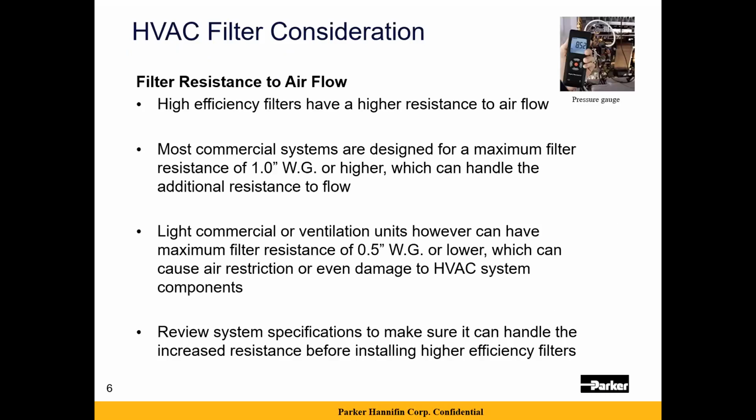So the first consideration is filter resistance to airflow. Generally speaking, as you increase filter efficiency, you will also increase that filter's resistance to airflow. Most commercial systems are designed, for single stage, around a maximum filter resistance of 1-inch water column or higher. And in those systems, you can handle that additional resistance to flow in most circumstances.